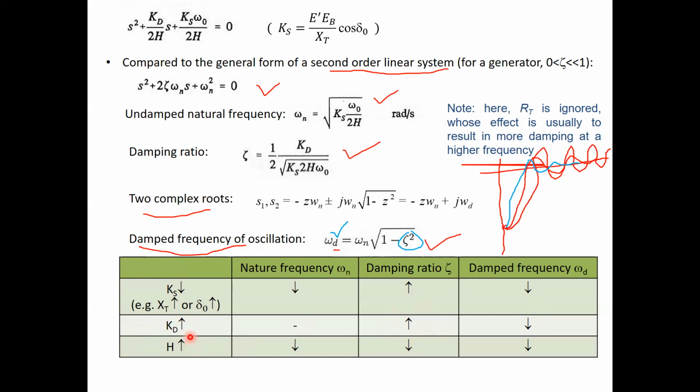And then again, you look at inertia, because you get inertia from a large generator, right? Steam generator, hydro generator. You don't get inertia from an inverter-based renewable, let's say the PV system, or even a full converter wind turbine system. So you don't get inertia out of those renewable resources.